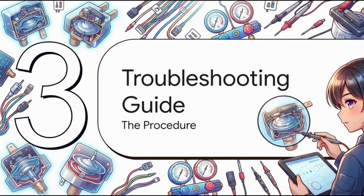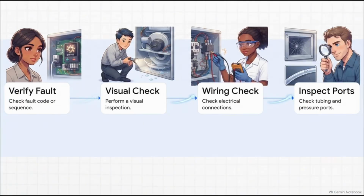Right, let's get into Section 3, Step-by-Step Troubleshooting Guide, the procedure. I want us to really absorb these initial steps because this is exactly where the detective work begins. Step 1, you must verify the fault code or the sequence of operation. Just sit back for a second and watch what the system is trying to do before you even touch a tool. Is the inducer even turning on?